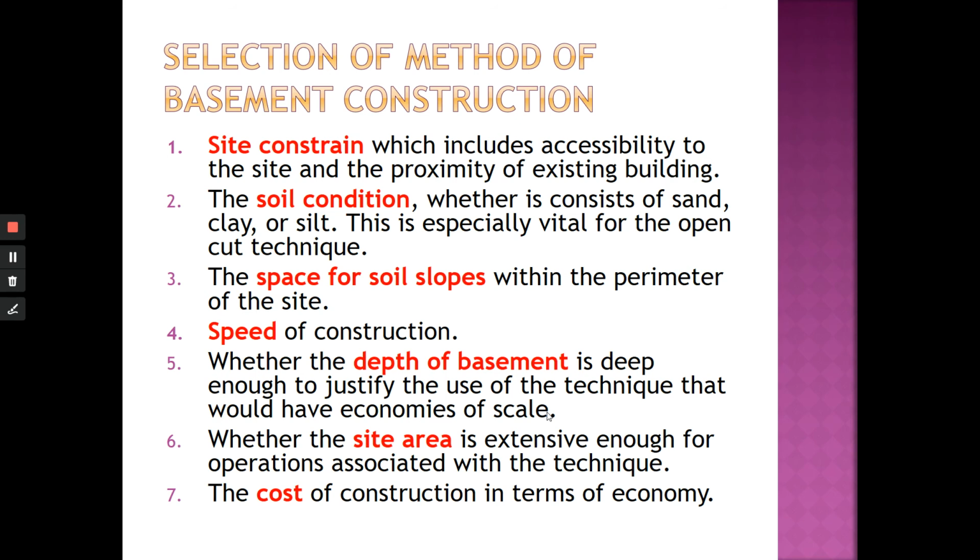Speed of construction. So you want it fast. The best method is top down or composite method. The fifth is whether the depth of the basement is deep enough to justify the use of the technique, that would have economies of scale.